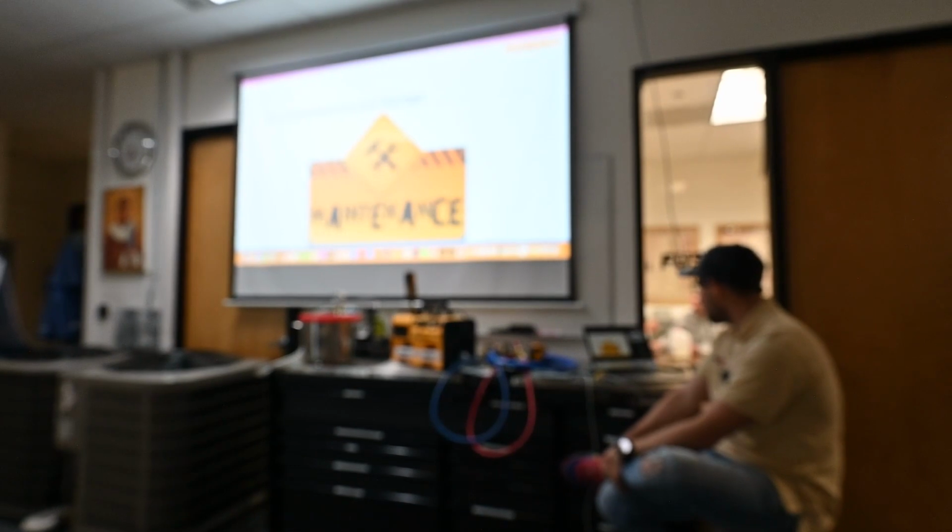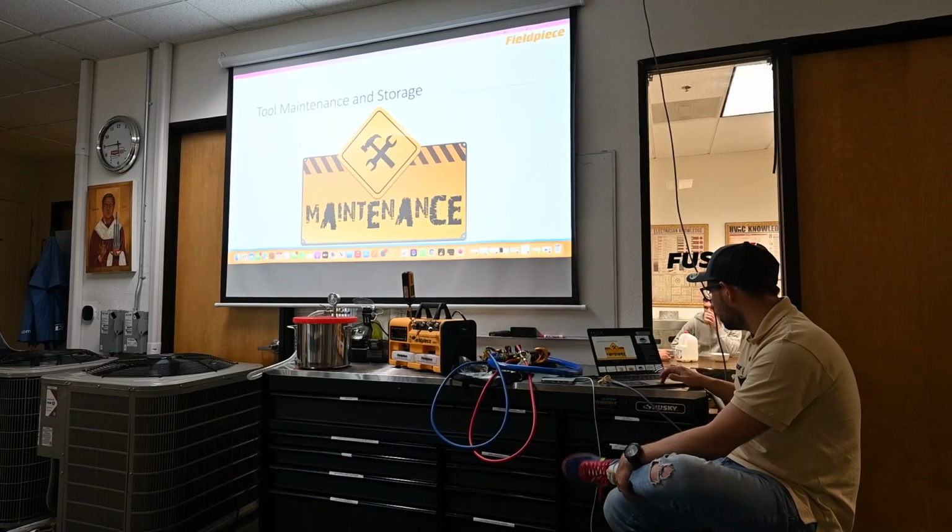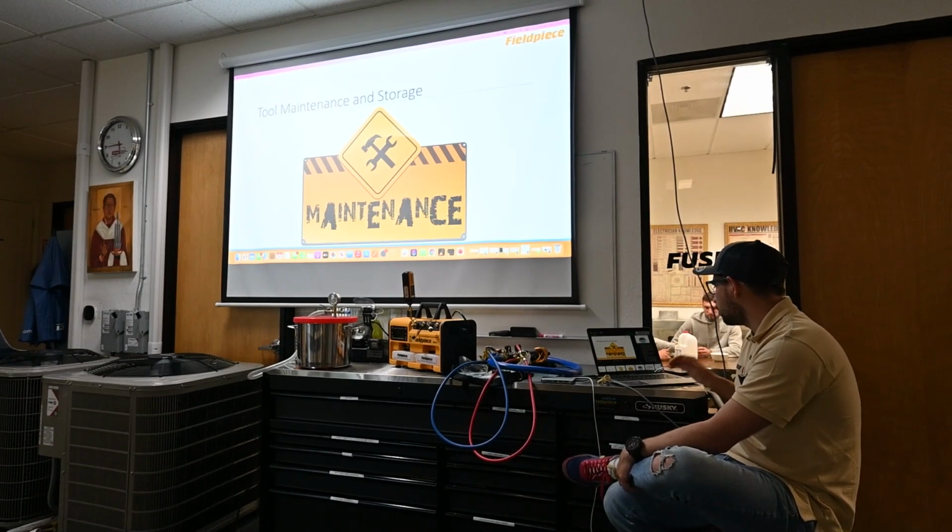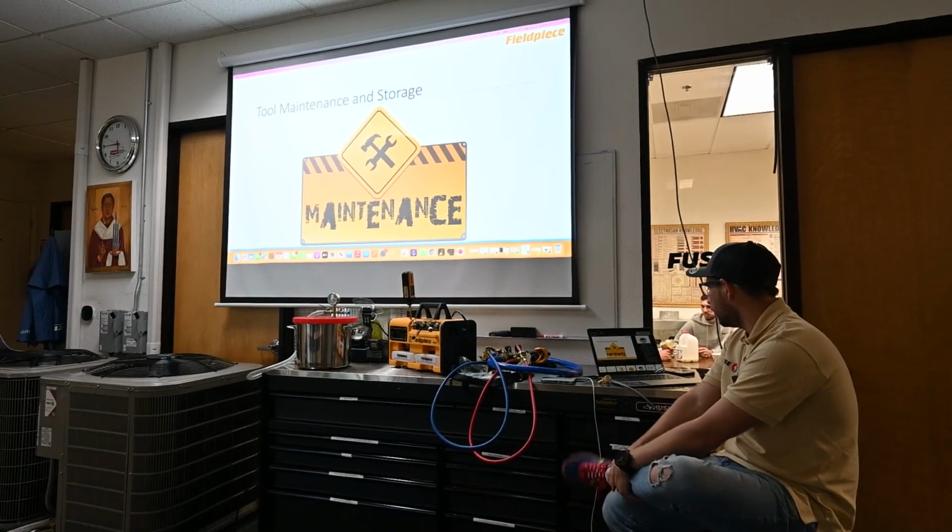Vacuum pump. Oil changes are needed, but not necessarily every time it is used. Use an uncontaminated vacuum gauge at the end of the job to evaluate the oil in the pump. If the pump will create a pressure down to 50 microns, the oil is in good shape and can be used again. If the pressure won't get to 50 microns fairly quickly, the oil needs to be changed.